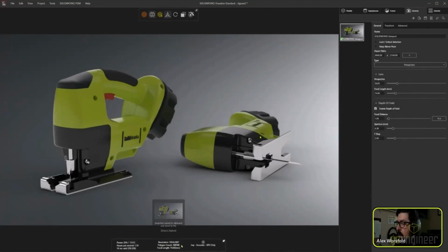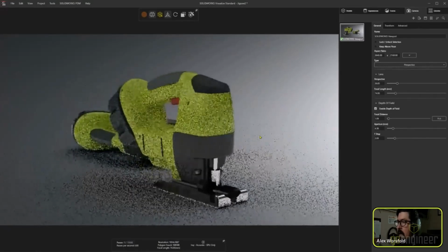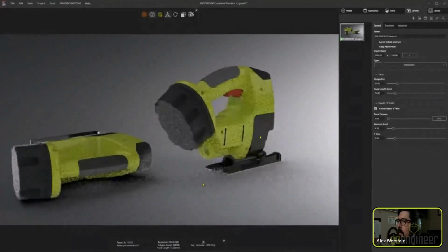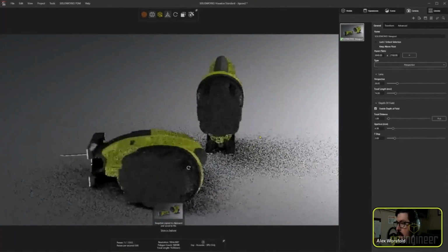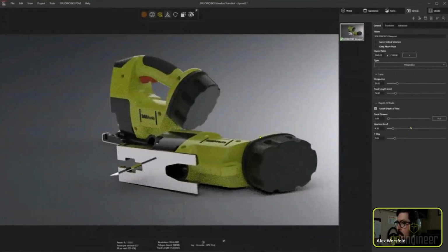Okay, so you notice that when I clicked OK there, it saved a snapshot with the current resolution and number of passes in my graphics area here. But now I can go ahead and just rotate to a new position, and then using Control and P on the keyboard, I can save a new snapshot into the same file and folder that I had picked earlier. I can even reset the depth of field. And then really all I need to do is wait for the number of passes to increase enough to where I don't see any graininess in the scene anymore, and then save another snapshot.